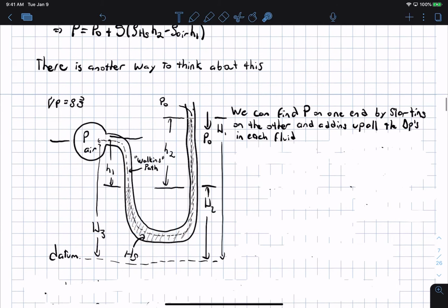And note, we cannot go through the tube like that. That is an invalid path, because we cross the tube wall. The static equilibrium condition for a fluid does not hold across the tube wall, because that's solid, and there may be a perfect vacuum out here if it's in outer space. So grad P equals rho g may or may not be valid out here.